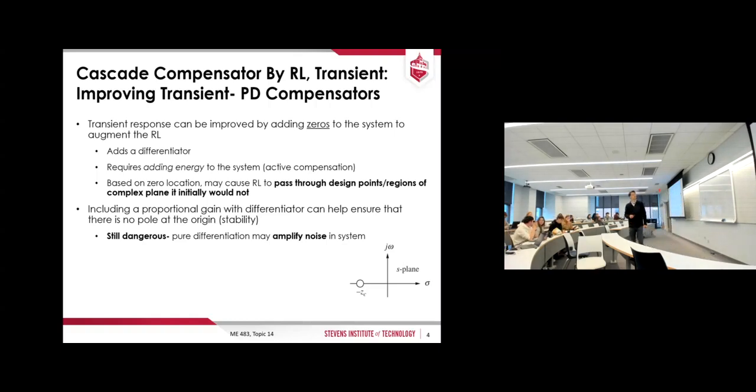All right, how do we do it? We include a proportional term, another one. So for the PI controller, the integrator alone was not used because of the stability issue, remember? So we added P, so it becomes a PI controller. Same for the D controller. A D controller alone is not used because it amplifies noise. And I'm not going to explain much. You would understand this better when you learn the Bode diagram and the frequency response analysis later this month, okay? But anyway, the bottom line is pure differentiation may amplify noise. Therefore, we use PD instead of D alone.